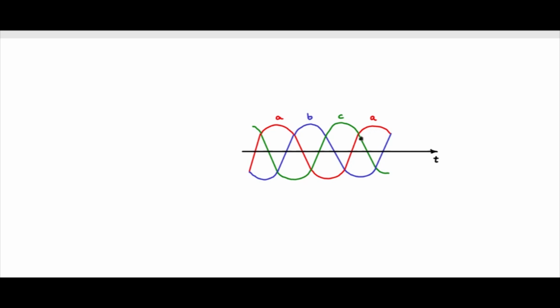So each is individually a time wave shape. Now this also can be represented in the spatial coordinates just like before. Now you can have three planes. A phase can be in one plane, let us say the horizontal plane. B phase can be at 120 degrees plane. C phase can be at another plane which is 240 degrees from the A plane. So their projections on the spatial coordinates will look like this.